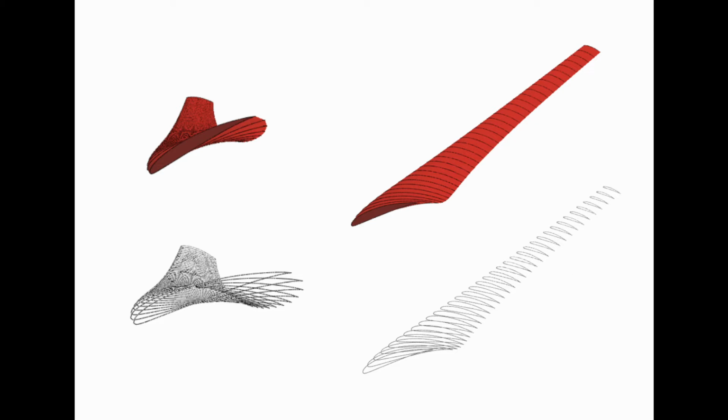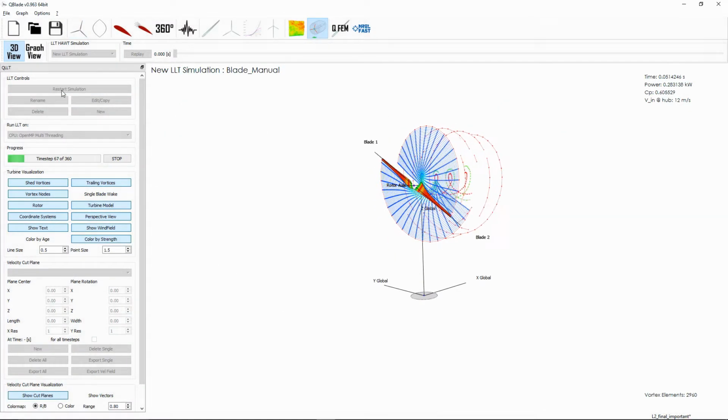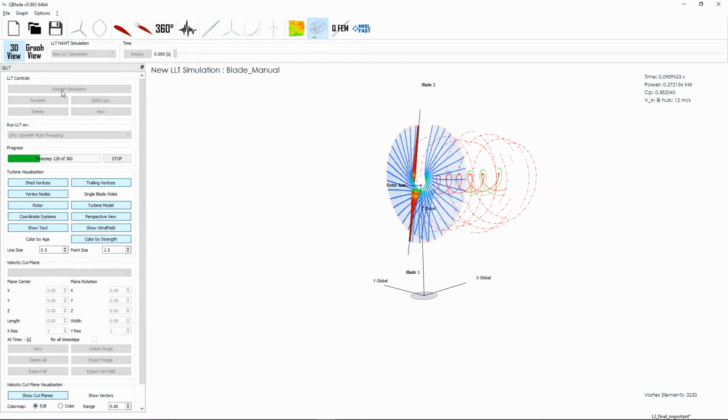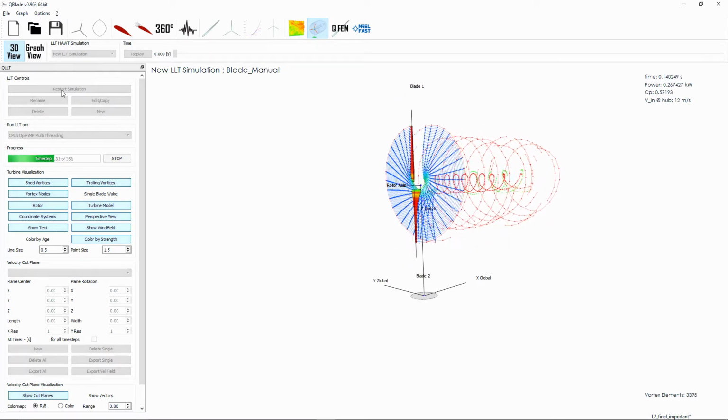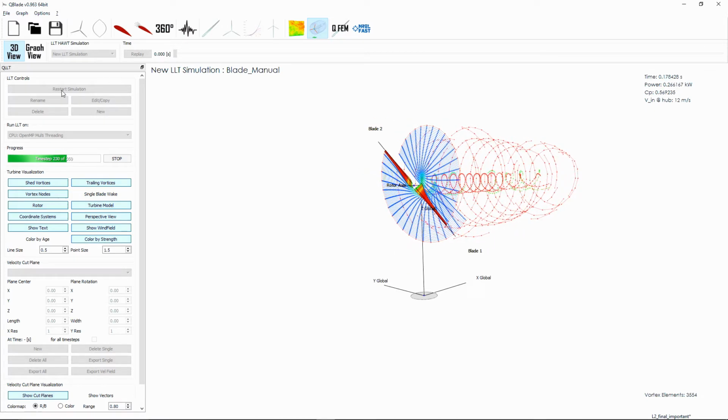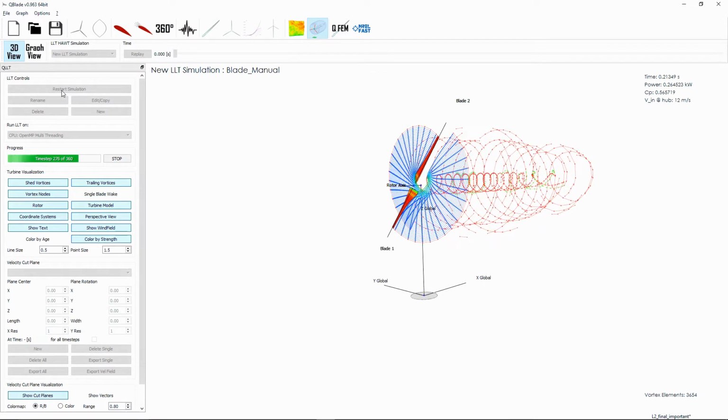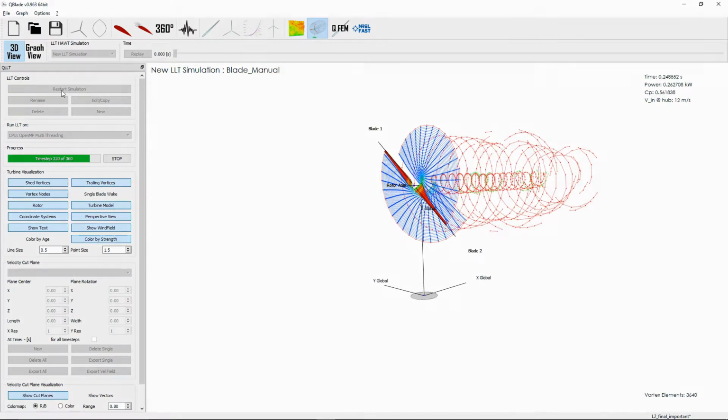Since tips rotate faster than the roots, their angle of attack with respect to the air decreases, so the blade needs to be twisted towards the direction of rotation to increase it. The best approach to decide the amount of twist is to plot L over D against angle of attack. Then check for the angle of attack that maximizes L over D, and use trigonometry to arrange the blades. The plots and the twist distributions were calculated using the open source software QBlade, which bases its simulations on the well-known XFoil. Finally, since the roots of the blades barely produce any lift, it was decided to go for a cylindrical shape. However, I leave that to my colleague Romain to discuss.